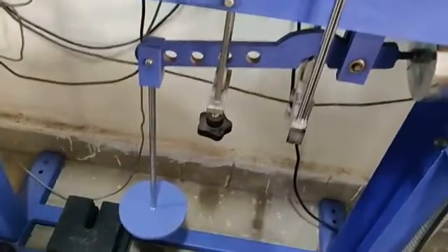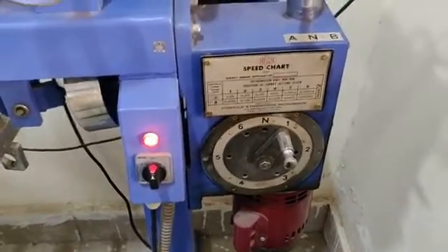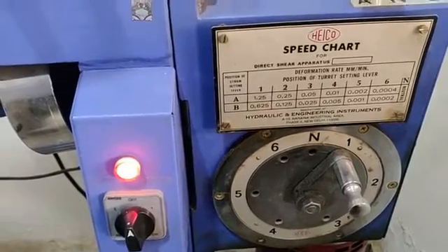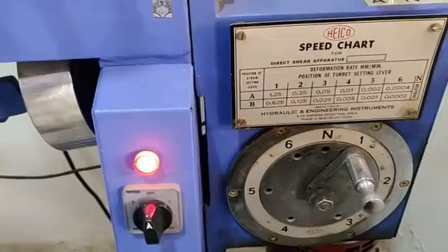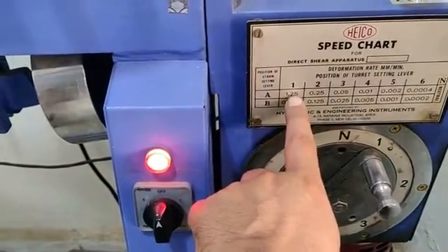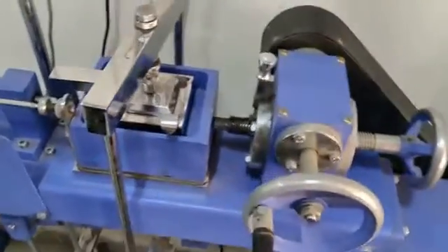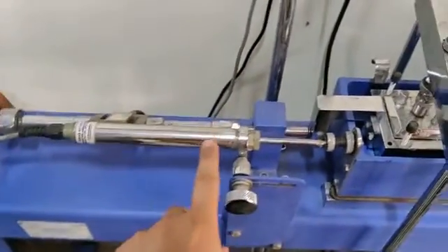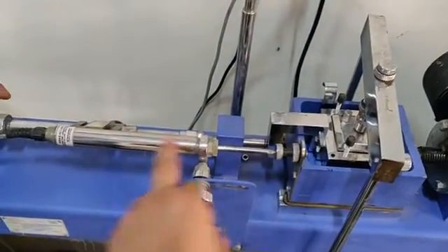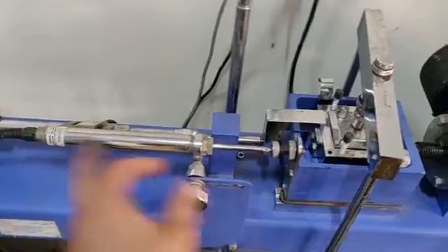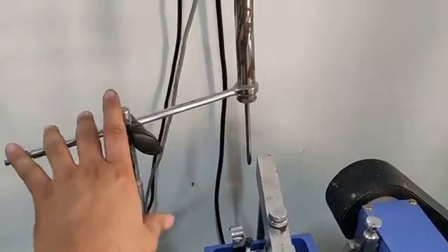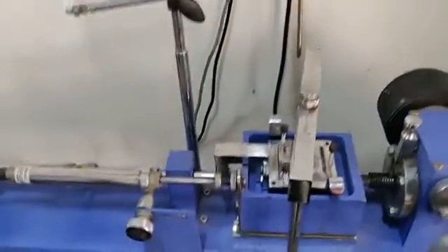Now I will show you the other parts of this. From here we are going to apply the normal stresses, and this is the gearbox from which we can change the gear, and from this we can change the speed. This A shows that 1.25 mm per minute deformation will be applied on this sample. We have placed this on first gear, and there are 2 LVDTs. This one LVDT is for calculating the horizontal deflection in the shear box. And this one we generally do not use; its use is to calculate if there is any vertical deformation in the sample.